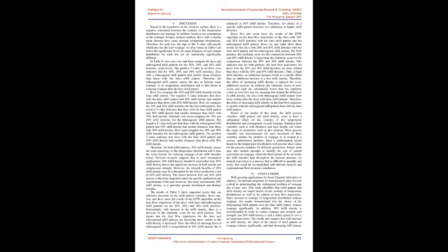The results of Table 5 show important trends that can influence decisions on the infill process variables. Rows 1, 2, and 3 show the results of the DTW algorithm on the heat flow trajectories of the disks with lines and trihexagonal infill patterns for the 10%, 20%, and 30% infill densities. Interestingly, with increase in the infill density, there is a decrease in the similarity score for the infill patterns.